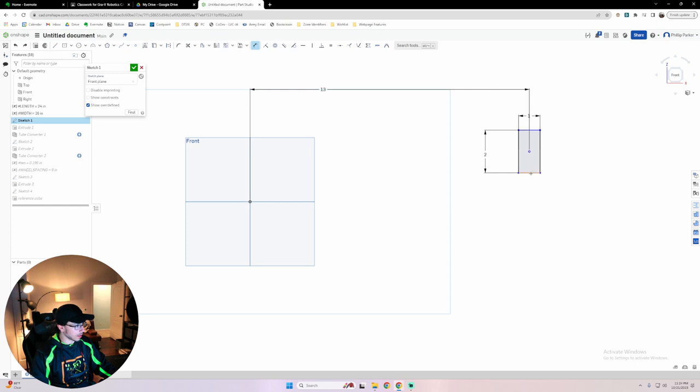It's the wrong dimension. I want it off this face. I want this to be 2 inches. Right? 2 inches or 3 inches. In this case, I'm going to do 3 inches off of the origin, and I'm going to do minus 0.125. I'm going to do minus, and I'm going to create a new variable: drop center.